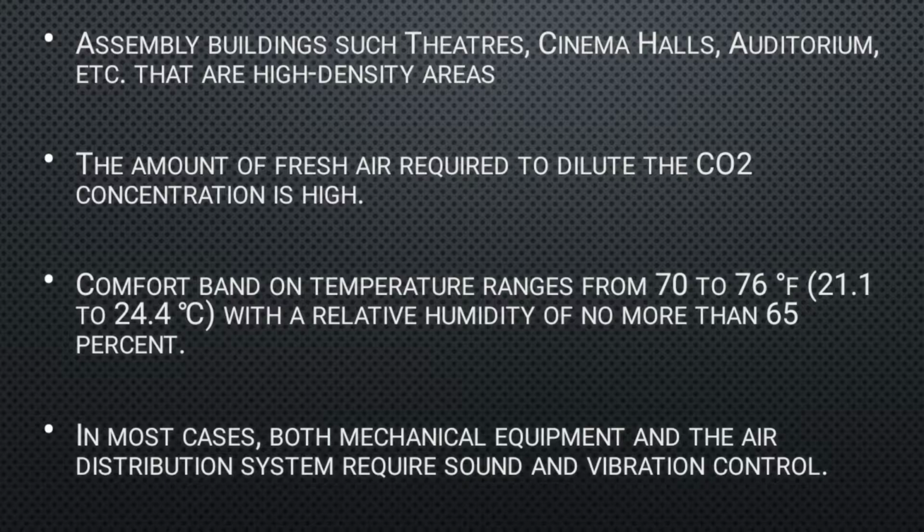Typically, the comfort band on temperature ranges from 70 to 76 degrees Fahrenheit, with a relative humidity of no more than 65%. The control of noise and vibration is also another important criterion. The desired noise criteria vary depending on the facility's type and quality. Noise control is less important in cinemas, but it is critical in theaters, auditoriums, and concert halls. In most cases, both mechanical equipment and the air distribution system require sound and vibration control.